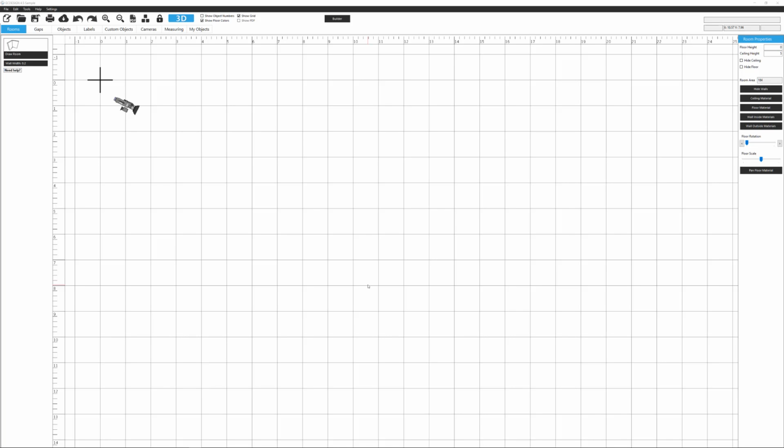Now we will teach you how to create your first walls and what will become your first very basic room. To start, make sure you are in the Room tab, because the Room tab is where you need to be whenever you're doing something with the room structure, such as creating, in this case, walls, rooms. Then you go down and click on the Draw Room button.